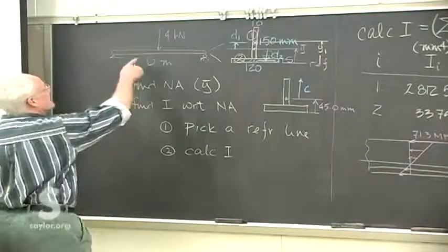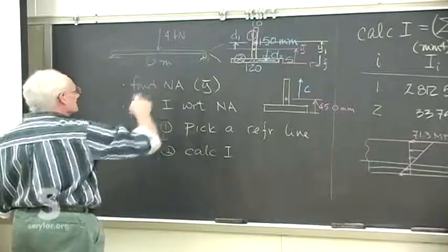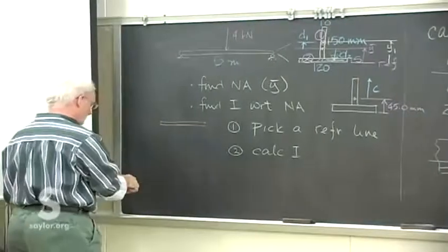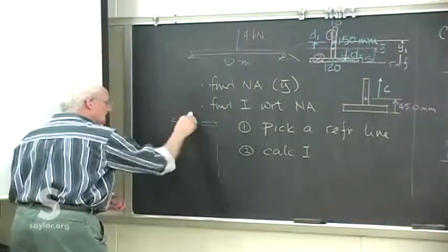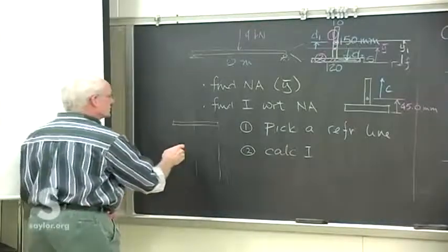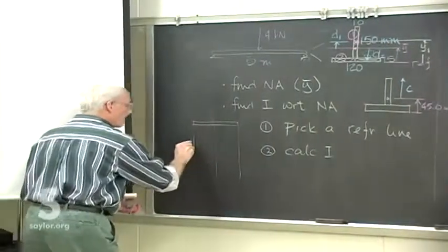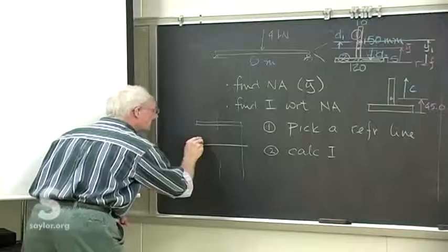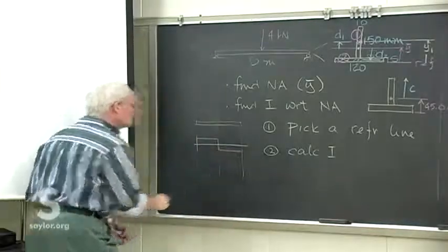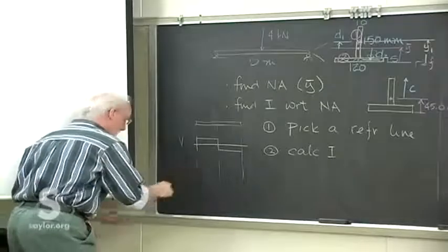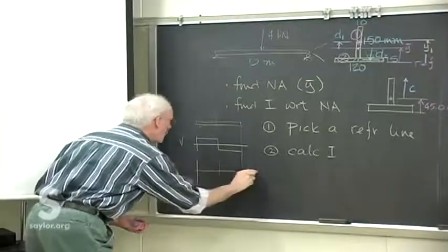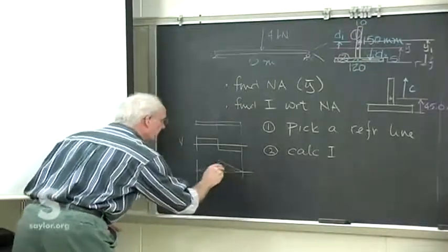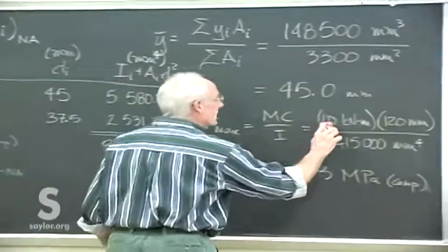Oh, okay, it is 5, because if we drew the shear moment diagram, we get a shear up of 2, only half of that, and then down to 2. So there's the shear, and then the moment is 2 times 5, only goes up to 10. So that's why we got the half. This was wrong. This should be 5.